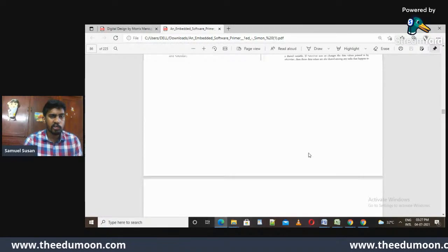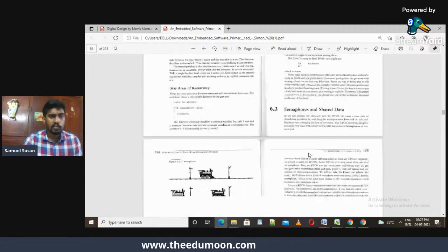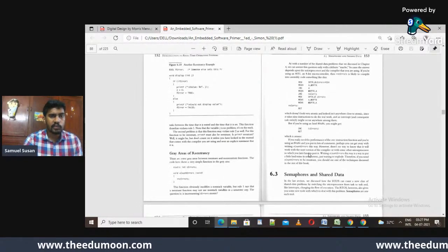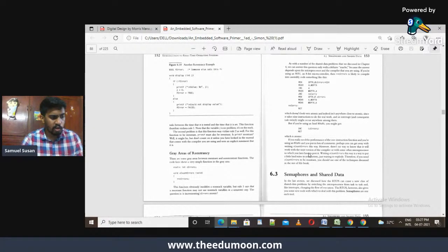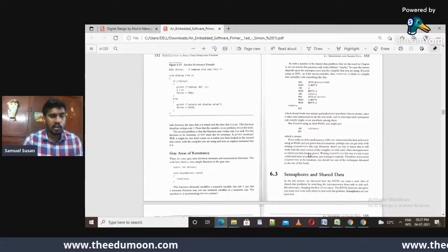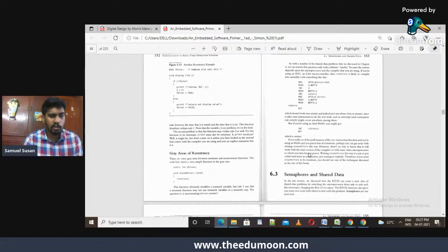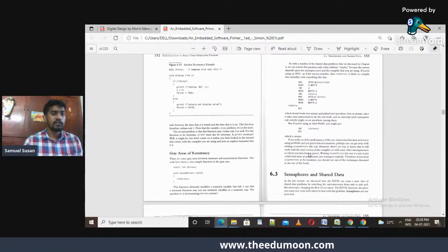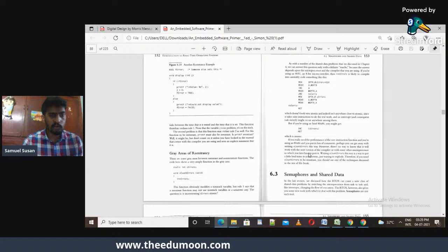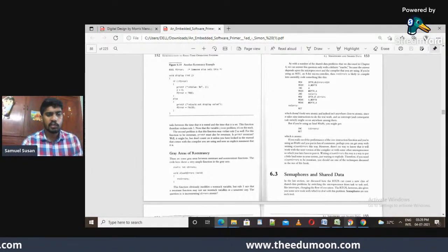Intertask communication systems, where we go with mailboxes, pipes, and queues. Right. One important thing we come across here, if you can note it down, is reentrancy. So what does reentrancy mean? If there is any code which can be called by many other tasks, which is common to everyone, right? The code which can be called by many tasks is called reentrancy code, right?